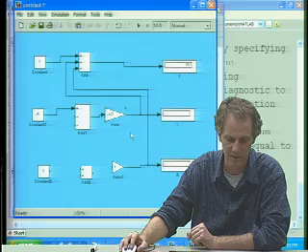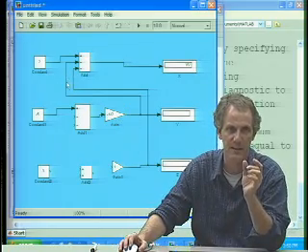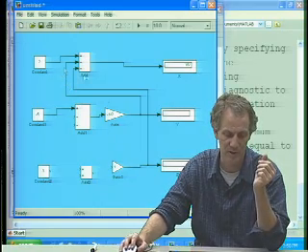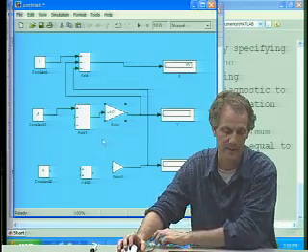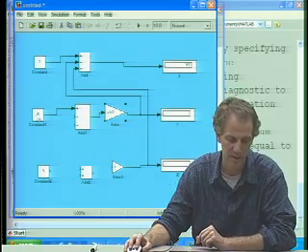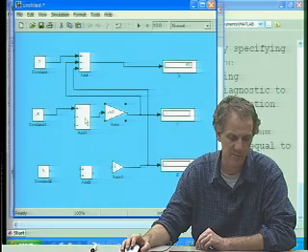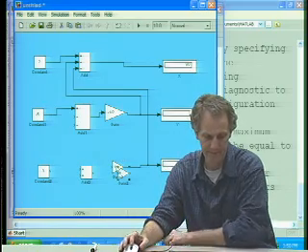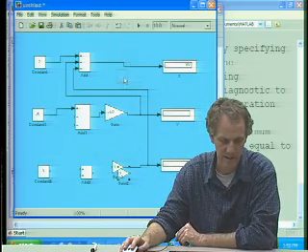Matlab will take the fractions as inputs. No truncation. When I first did it, it had a little k there. K is Simulink symbol for I don't have enough space. So I made my triangle a little bigger, and then I was able to read the number negative 1/2. All right, so that's the constant in that second equation. The next thing was a negative 3x. For that, I'm going to need a gain. I'll put it up here for my x variable.